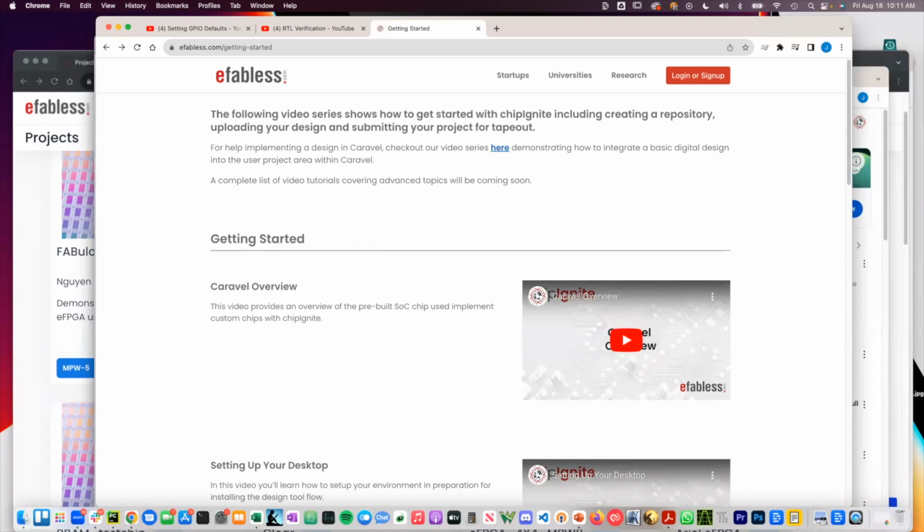If you want to use the Wishbone port, you need to create the slave port logic, so you need to create the Wishbone to register interface. And I will say that creating a version of the Wishbone to register interface takes about 3 lines of prompt with generative AI. So it's not a hard problem, and it's usually correct because there are many, many examples of the Wishbone interface in the public domain at this point.